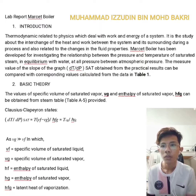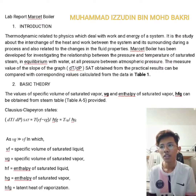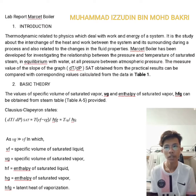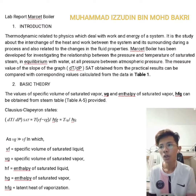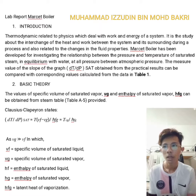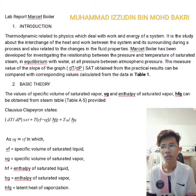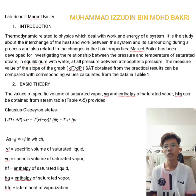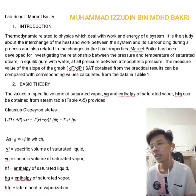The Marcet model has been developed for investigating the relationship between the pressure and the temperature of saturated steam in equilibrium with water at all pressures up to atmospheric pressure. The measured value of the slope of the graph, delta T divided by delta P saturated, obtained from the practical result can be compared with the corresponding value calculated from the data in table 1.